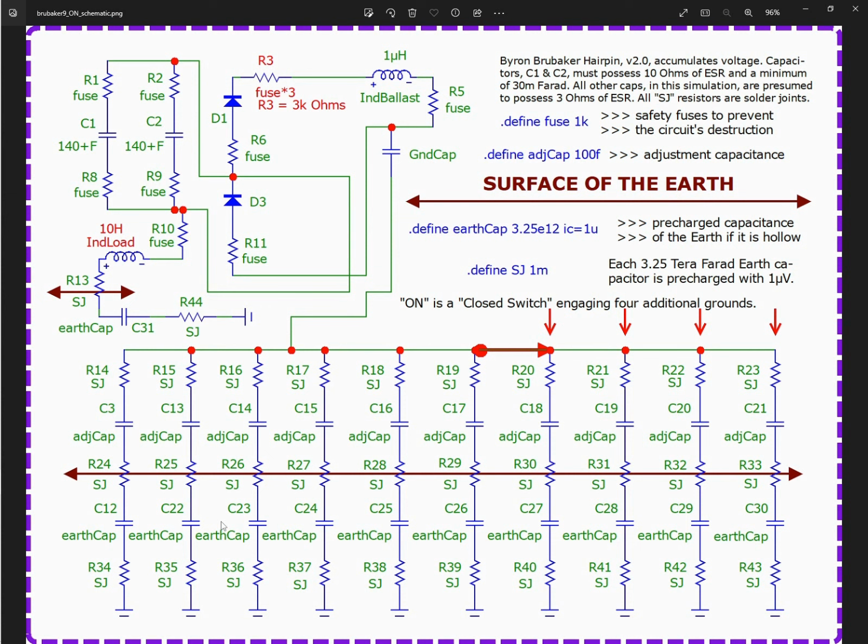That changes everything. So I took out those 2 diodes, so now it's no longer a bridge. You know what I'm thinking? Just now I should have taken out these 2 diodes and see what happens. But then we'd lose our DC loop. So the whole point is we have a DC loop and we have an AC loop. And the AC loop goes in between the 2 diodes like it traditionally does. And these 2 diodes make sure that the DC loop always goes in the same direction. And so that's all I retained.